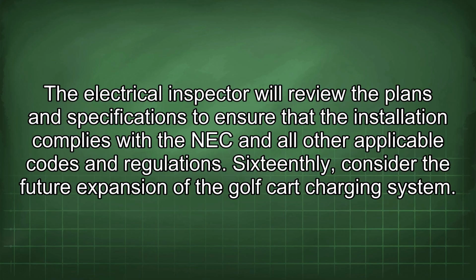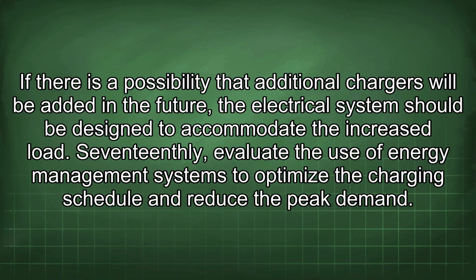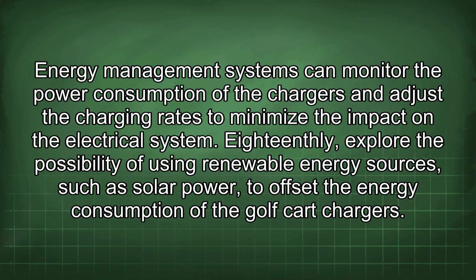16thly, consider the future expansion of the golf cart charging system. If there is a possibility that additional chargers will be added in the future, the electrical system should be designed to accommodate the increased load. 17thly, evaluate the use of energy management systems to optimize the charging schedule and reduce the peak demand. Energy management systems can monitor the power consumption of the chargers and adjust the charging rates to minimize the impact on the electrical system.